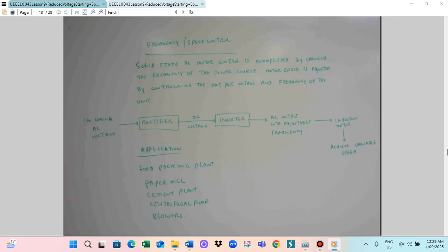So as I said, I talked about the motor speed control. After that, I will continue with speed control by the frequency changing method, and also jogging, plugging, and braking. Jogging means the step-by-step movement of the motor, which we especially use for the crane motor. Plugging means that we want to stop the motor instantly, so those are the braking method and the plugging method.